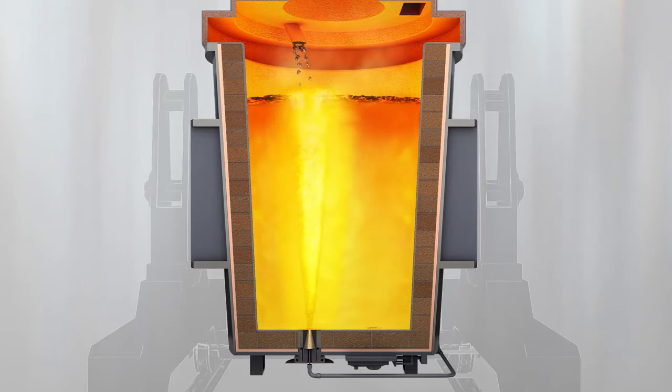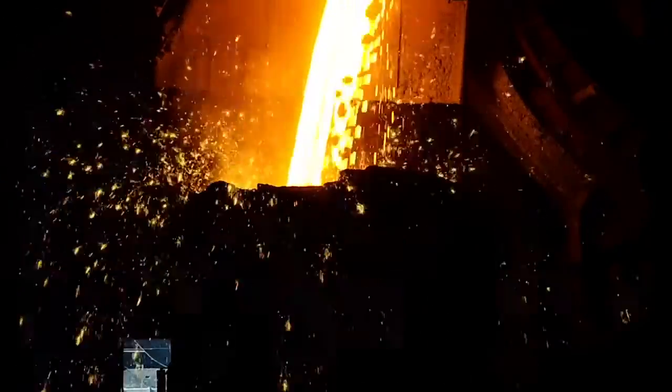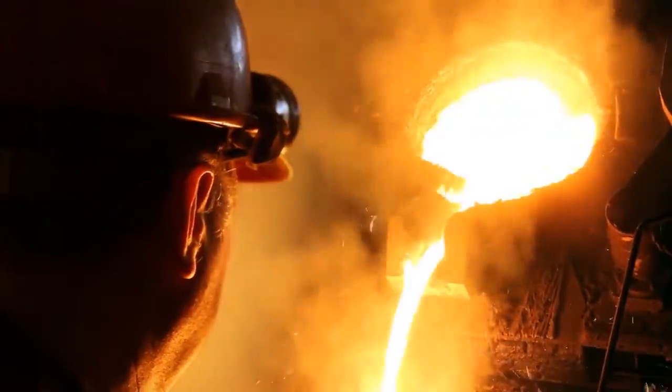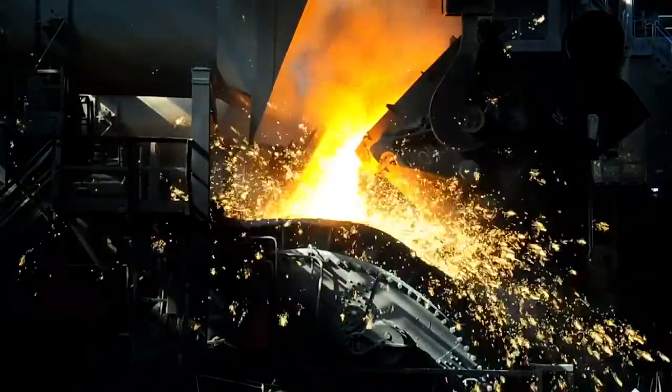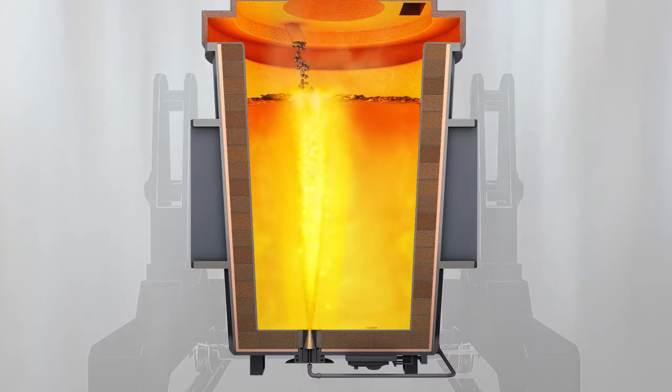During the time the liquid steel spends in the ladle, a thick slag of iron and oxide-rich material forms at the top of the melt. A hole must be formed in the slag to allow the introduction of the various additions, including the ferroniobium. Depending on the steelmaking process, to enhance the yield of niobium, the ferroniobium can be added during tapping in the early stages of ladle filling from the primary steelmaking vessel, or at a later stage when the ladle is full and further deoxidation has occurred.